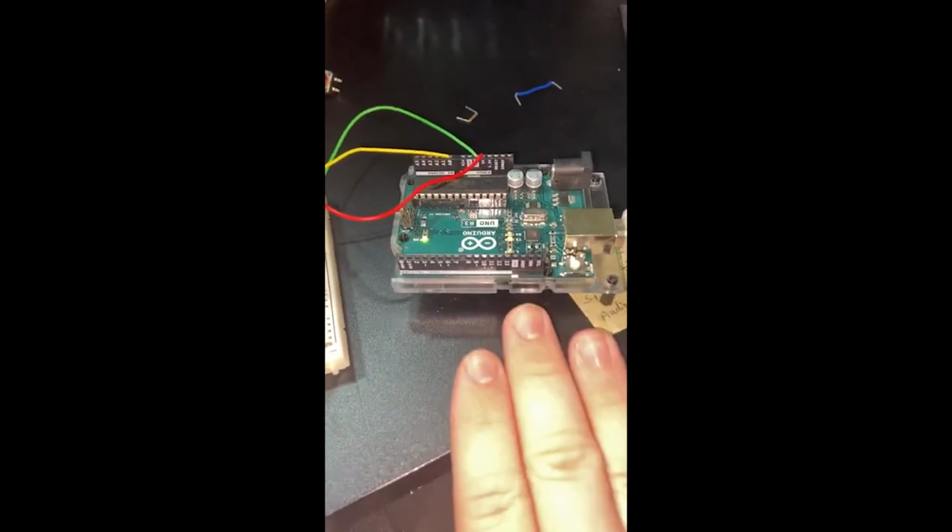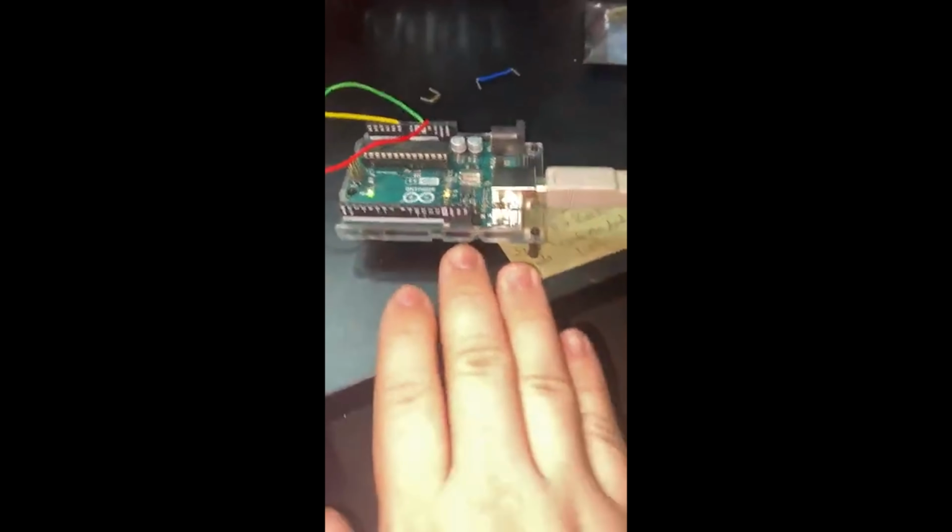So I've got the math related down here. If you measured that output voltage, you start with what you had and you multiply it by these things. But basically, as you change one of them, it changes that relationship for that output voltage. So again, by keeping a resistor and the normal voltage constant and changing the other resistance, we can change how much electricity is being sent to the Arduino pin, and then again the Arduino can respond to that.